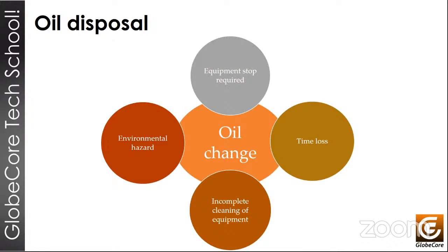Now, I mentioned that the contaminants from the transformer will contaminate the new oil. And basically in under 1 year, you will have the same quality problems with the new oil. So what happens is that this process of changing oil basically generates oil waste, and it wastes time. And it's a process that does not achieve any long-term results, really. So if you compare all the costs of oil change, the cost of oil regeneration actually becomes cheaper than oil change and oil disposal. Next slide, please.